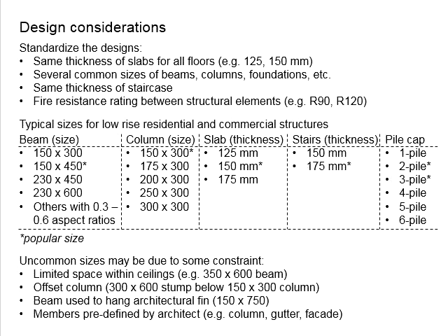should be sufficient. And you have to consider also when you design the staircase, whether you have any mechanism to transfer the load from the landing beam towards the ground. If not, the stairway may behave as a cantilever, or the load will be supported by the joints to the floor plan of different levels. In this case, most likely you require a thicker staircase.